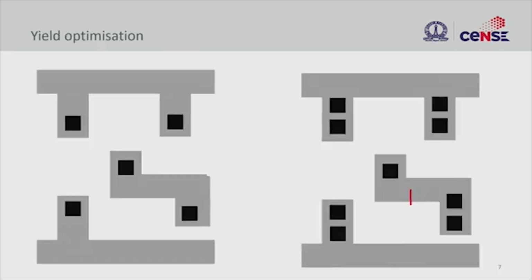So the next thing is about interconnect itself. We briefly introduced this earlier, but let's look at what is the problem here. So you normally do some contact like this, right? You have a single point contact, and then the important thing is to place these contacts at the right clearance from the edge.